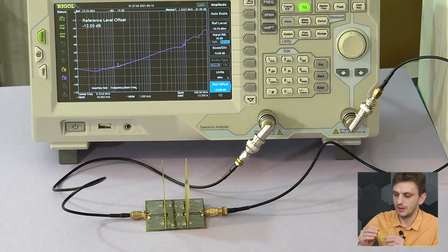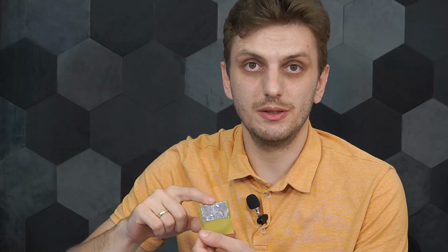The main issue is that our floating shield is coupling quite well with our initial noise emitter and thus creating stronger electric fields to our sensitive receiving circuit. So if you add a floating plate to an electric field noise source or to an electric field sensitive circuit, you're gonna make things worse.